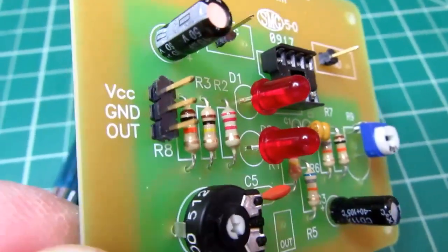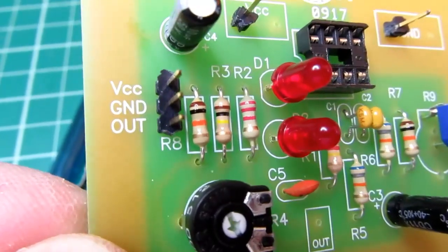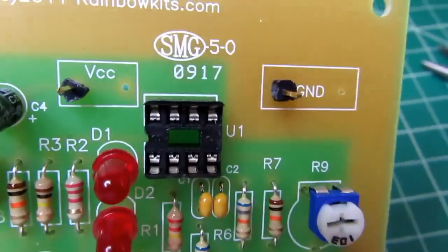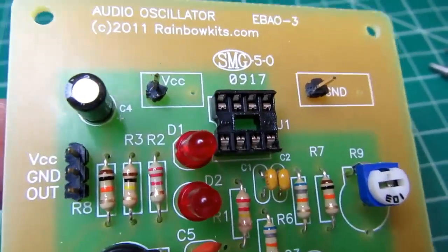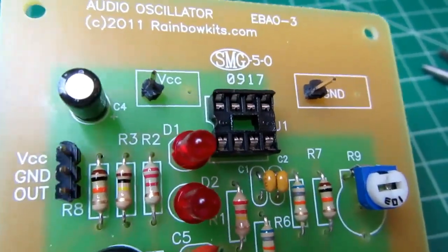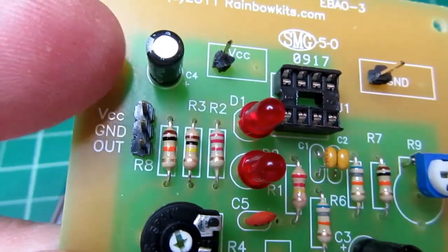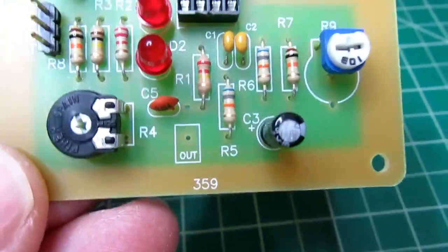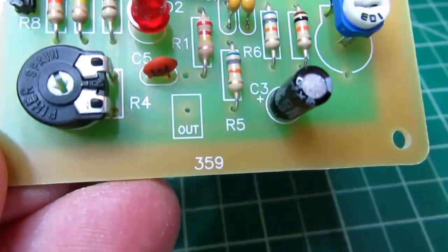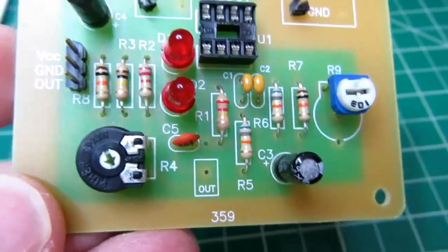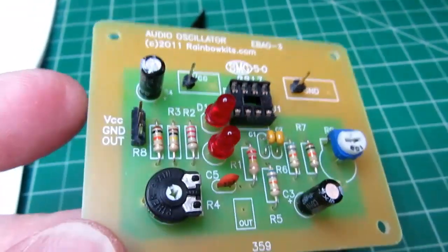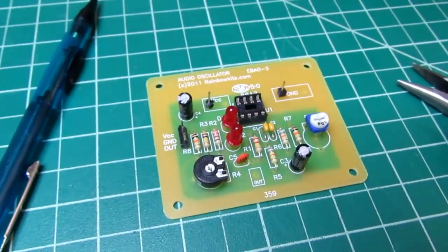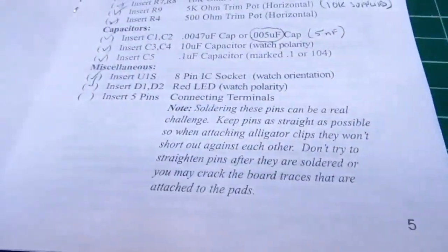Okay, I put in three of the pins over here on the left, which has VCC, ground, and out. I elected to put one pin each in the dual holes for VCC and ground, just in case it's more convenient to apply power separately and then just use the output pin over here. But I could also run a single cable that does everything. The other holes for VCC and ground and the one hole for out here could be used to solder wires into and still leave the pins. So I think this is a fairly rational way of compromising between what's supplied and what the board layout is. Be nice if the instructions said anything at all about that.